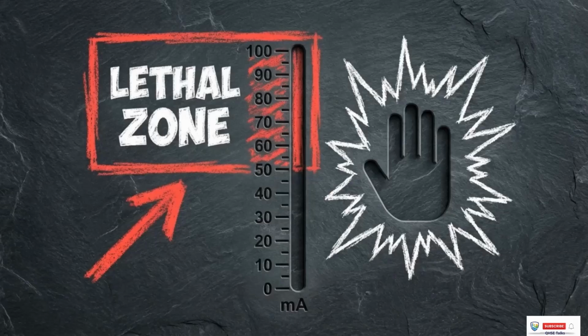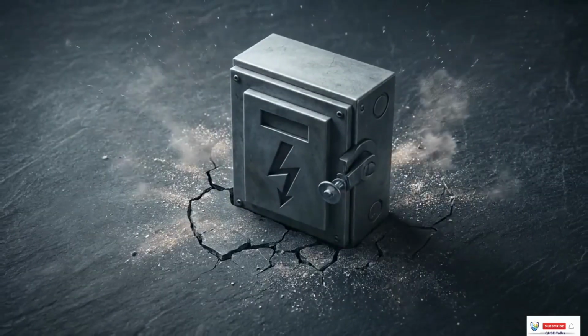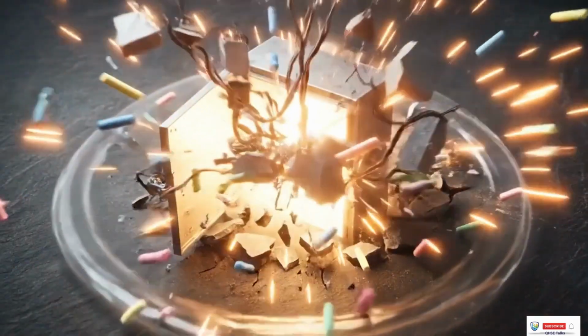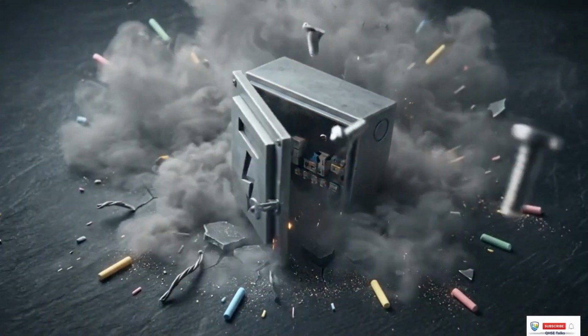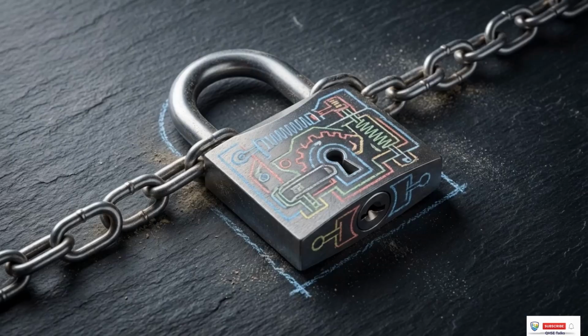Between 50 and 100 milliamperes, the current triggers ventricular fibrillation. This disrupts the heart's rhythm, leading to respiratory paralysis and a high probability of death. This high-speed depiction shows an arc blast. Secondary hazards include internal thermal burns and explosions generating metal vaporizing heat and lung-collapsing pressure waves. Human lethality occurs at mere fractions of an ampere. Relying on standard equipment protections to prevent human injury is a fatal error in safety management.